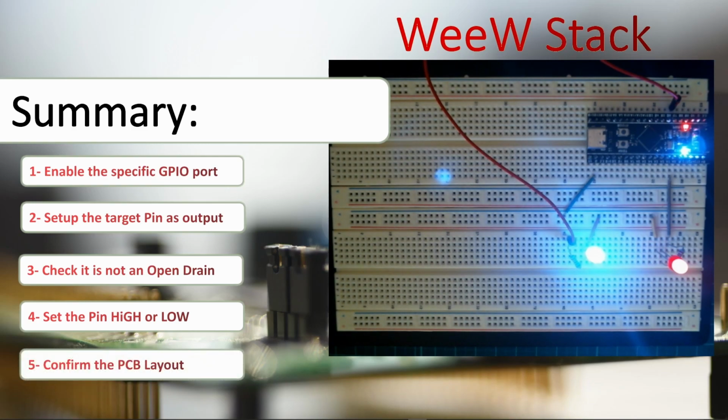And the last point, we had some issue with the final LED, the PC13, and this is because within the circuit it was active low. So we needed to confirm our PCB layout to understand the electrical circuit that we are working with.